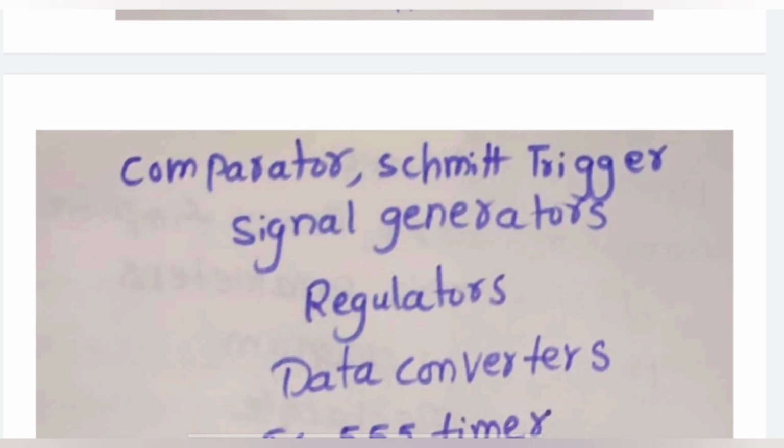We will see different types of phase detectors, like analog phase detector, in which we will get only half wave, hence it is called as half wave phase detector. And we will see how to get a full wave phase detector. Then we will see digital phase detector, where we can do using XOR gate or edge triggered. Then we will see what is voltage control oscillator VCO, which generates the free running frequency F0, its pin diagram and functional diagram. Then we will see what are the different filters.